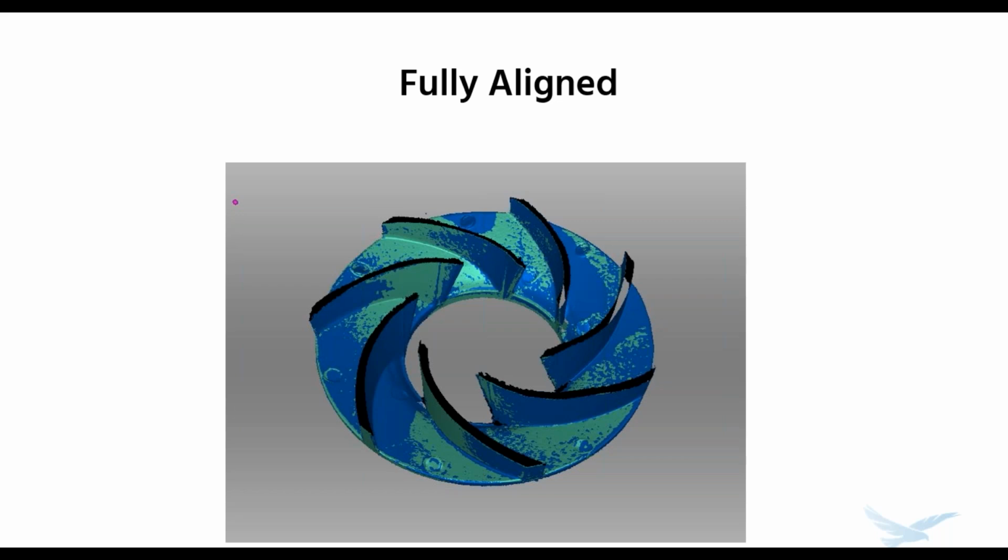The very best solution for hole locations is going to be one of those arms that you saw, because you can simply nest that circular probe into a small hole, or you can trace a big hole with the probe, and that is a very quick, very accurate way of measuring hole locations. There's really nothing that beats it.